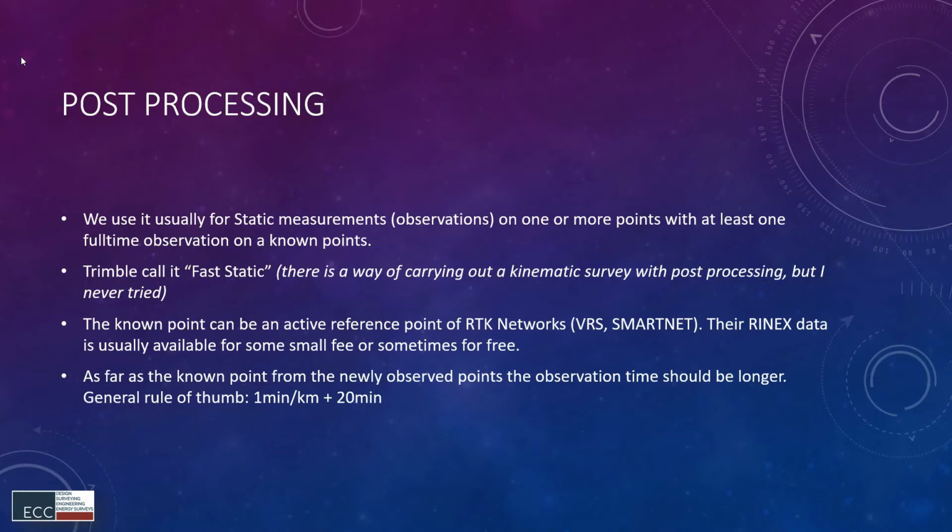You have to do some settings on the interval, like how many seconds you want to store the epochs, and where you want the receiver to log the data.